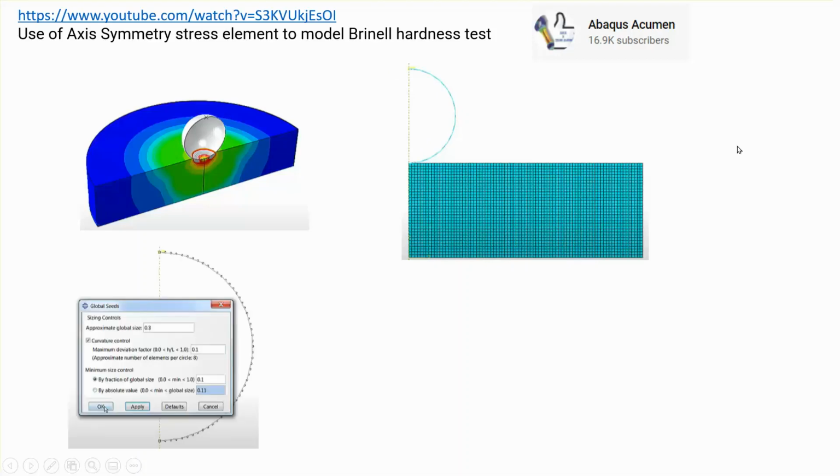Okay, so you see a workpiece here and an indenter that is pressing against it. I will model this indenter only as basically a curve which is going to be pushing against the workpiece. Now I will use the same element sizes that this gentleman is using, and nonlinear geometric effect is on.